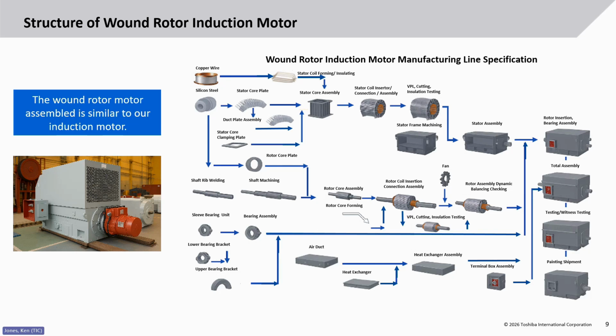They use a mica tape as well as a VPI epoxy resin as part of the design. When completed, the motor is still Class F insulated, but usually has a higher insulating capability than the 150 degree temperature condition. It's typically 180, so it's Class H.